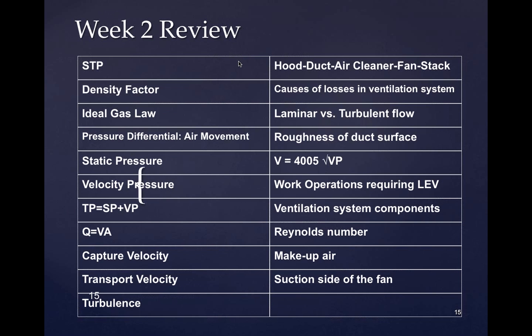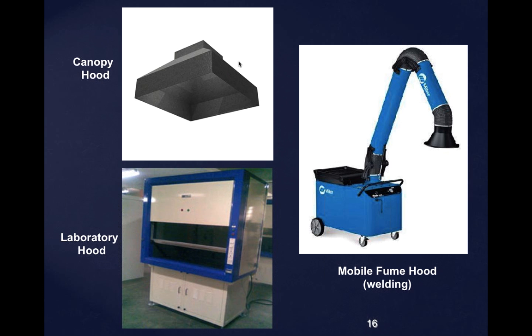So if you have exactly the right velocity of air going into that thing, then you can predict that particles over a certain size are going to get trapped before they go to your filter and get counted as part of your particulate matter, your gravimetric analysis. So you can predict, oh, well, all I'm going to get going onto that filter is going to be the particles smaller than, say, 10 microns or 4 microns, or whatever it happens to be designed for.